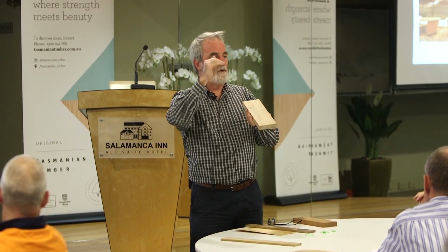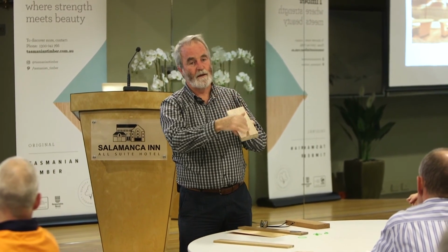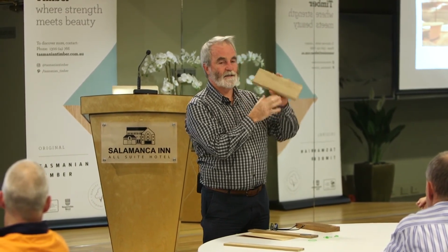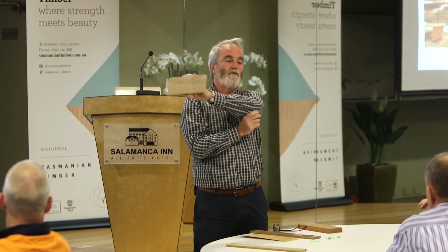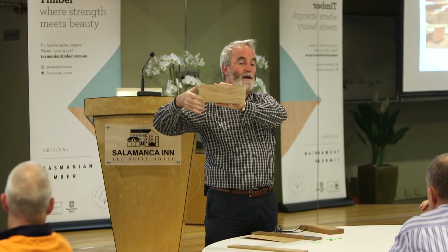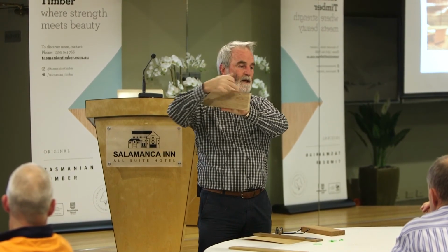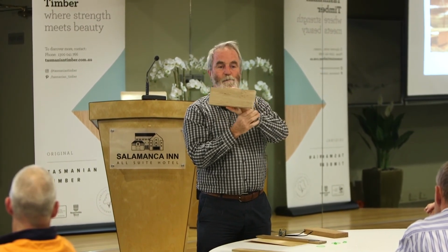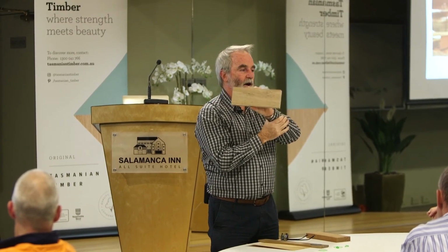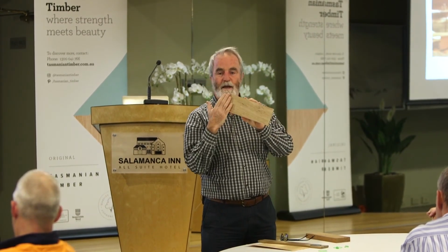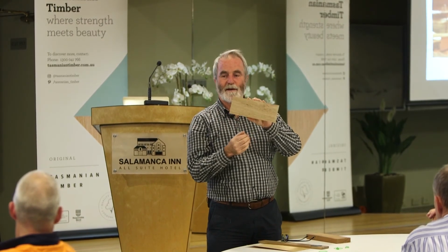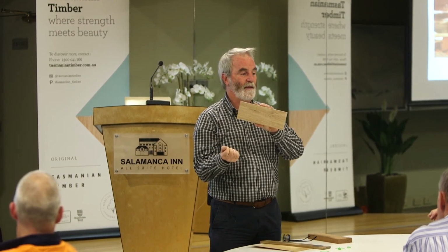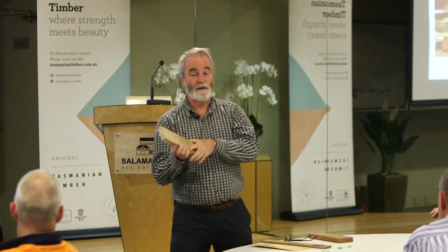Also, the sunlight will hit the molecules of the wood and it will break them up. So if we leave this outside, put it on the fence, it will go grey. And that greying is the molecules being broken down by sunlight and they lose their colour. Now, if we've put a clear coating over that, the clear coating lets the light through, sticks to the surface, but then the surface becomes all chalky and the clear coating falls off. So that happens all the time outside.